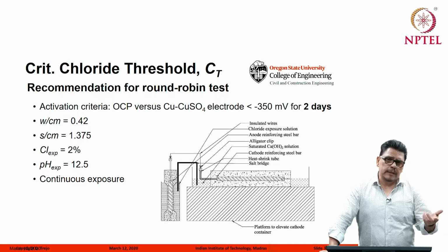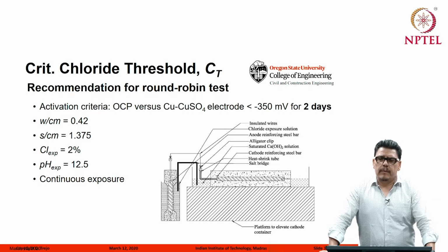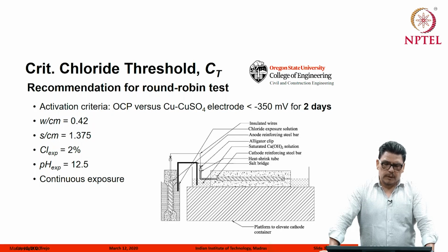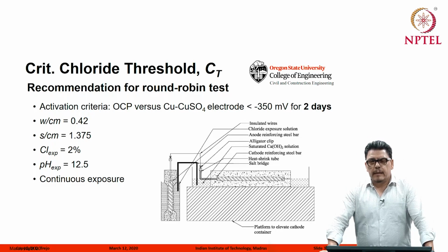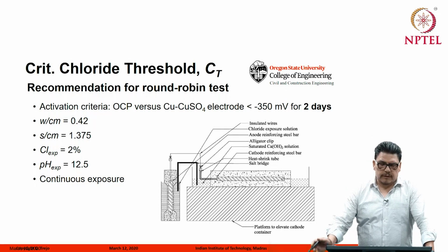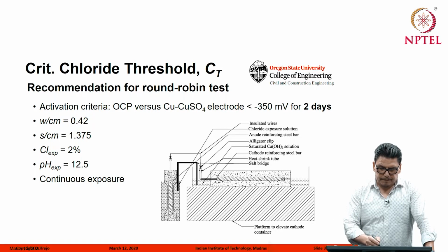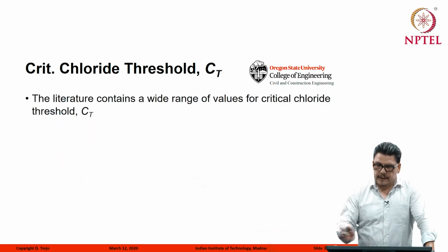We did that for several reasons. First of all, it's easier to handle and more economical. There are many places where testing is very expensive, so we decided to do a continuous exposure. We think we should have results from this fairly soon, but this is a standard test that we can use for assessing the critical chloride threshold, and this is important for reasonably predicting the time to corrosion and service life. It's a start.